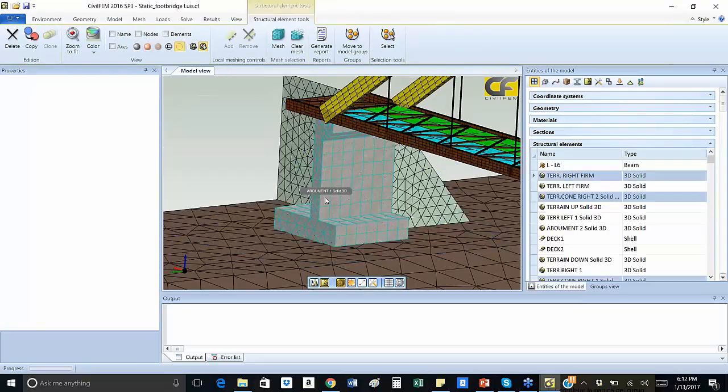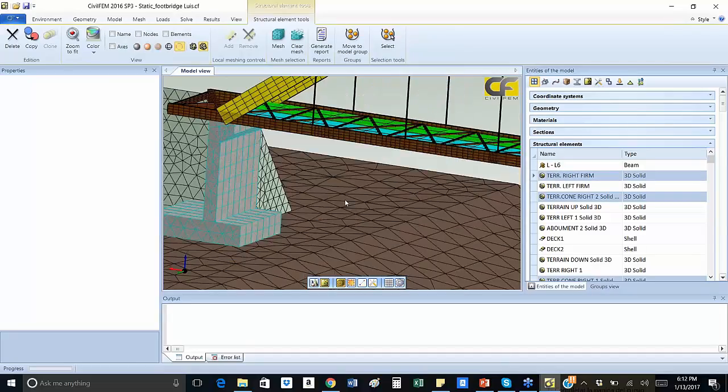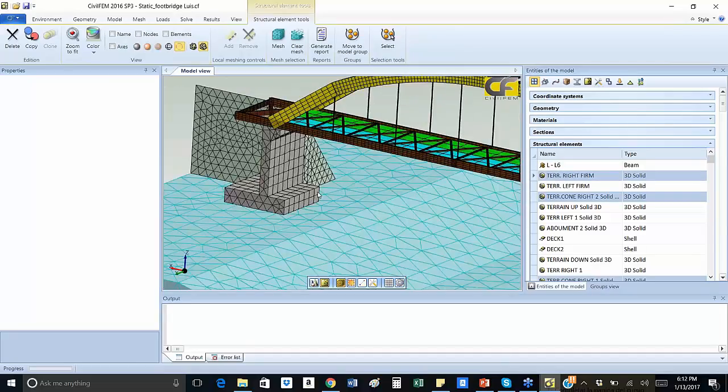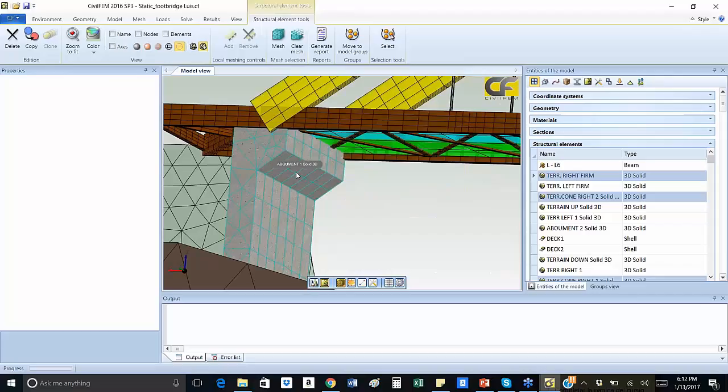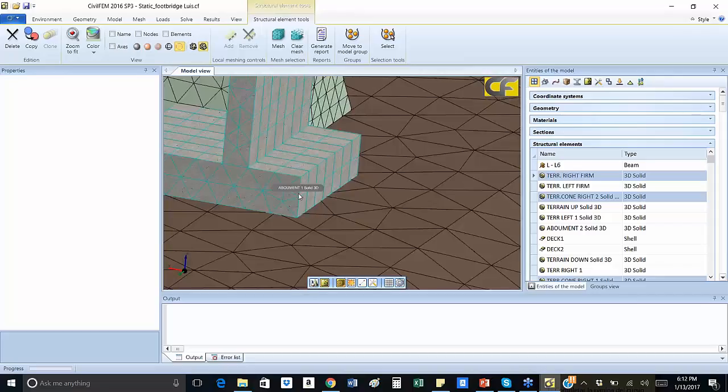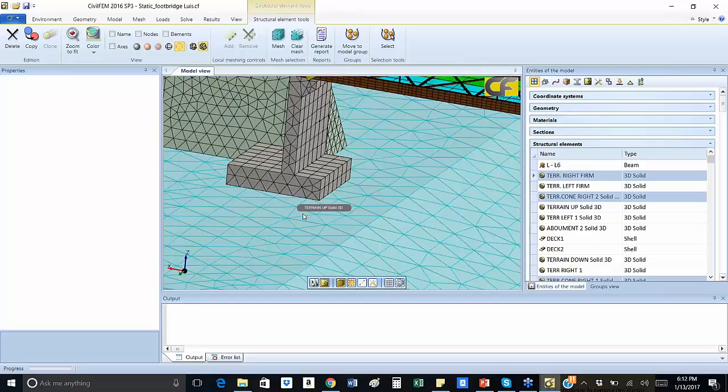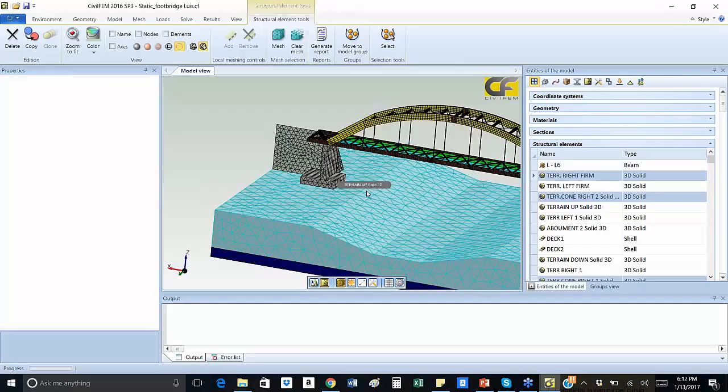That's the soil. And we remove that to make visible the actual reinforced concrete abutment. The loads are transferred directly to the soil via the abutment. And notice that different components are touching, therefore you have to create a contact model.